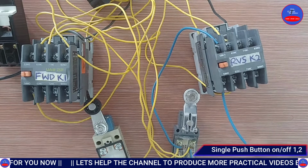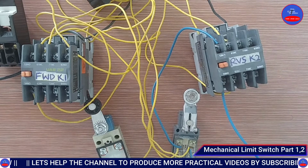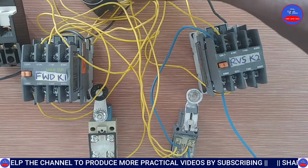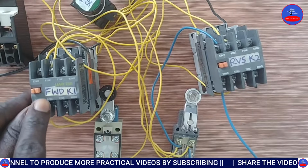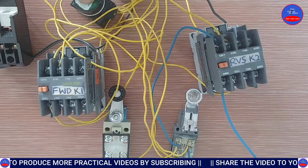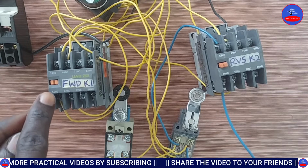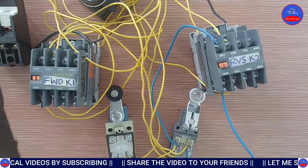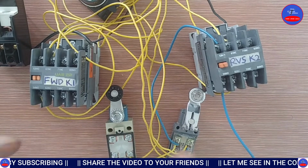Right, I've turned on the main breaker. So let's test the circuit and see. We're going to press the forward push button. Let's see the contactor K1. See that it is in now. It is energized, right? So now the conveyor is moving in this direction. It is moving in the right direction.